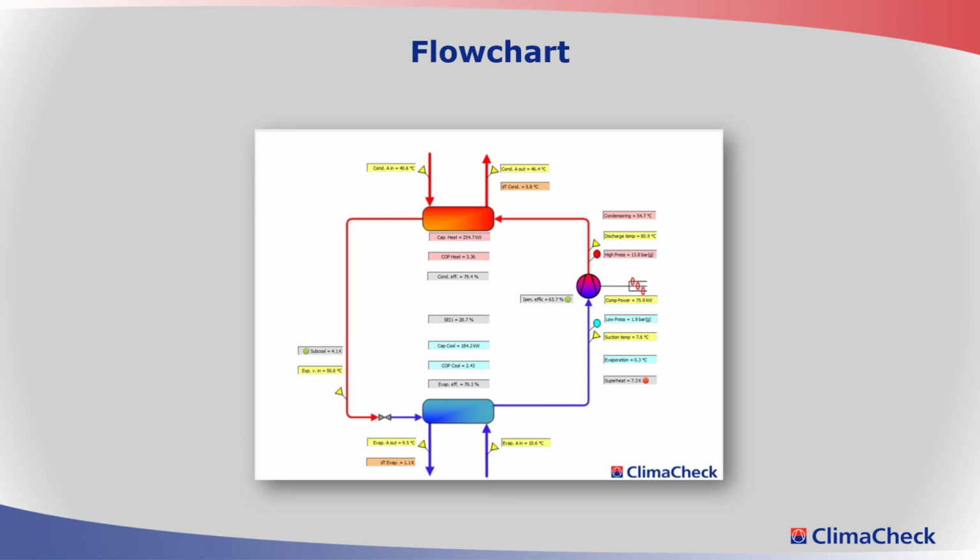So we need to think about that this is the last value that has arrived to the software. It might be a good data to represent our system, but it might also be when the system has just been starting and maybe not used as a representative data. So in here we have the live data from the sensors: temperature, pressure, electrical power. But we also have the SEI and the sub-efficiencies: compressor, condenser, and evaporator.